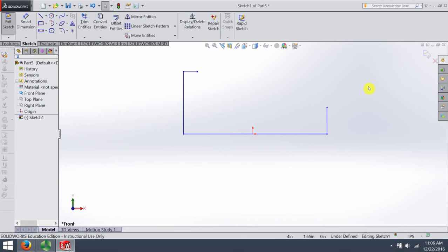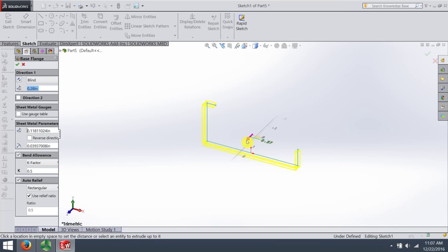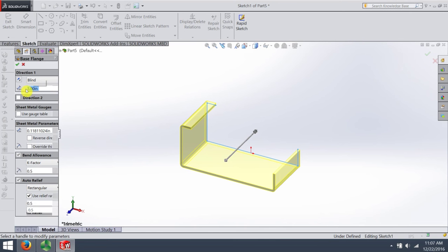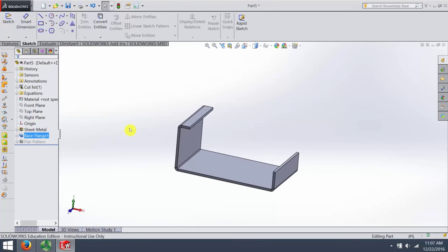And the nice thing about this setup is this whole thing now is a piece of sheet metal, and I can get all these flanges at once. So let's see what we've got there. Let's make that 3 even. Okay, so obviously quicker. I don't have to make each individual flange. I don't have to bend anything. I can get it all in one operation.